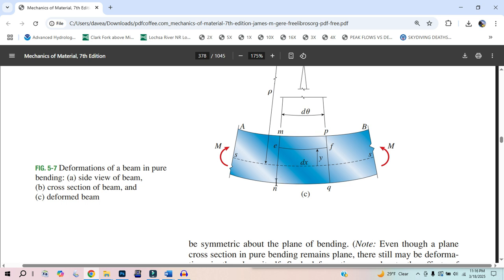so that change in length is going to be a change in length of 2. So the change in length is length final minus length initial. So you'd have 1,002 millimeters minus 1,000, and so you'd have 2 millimeters. And strain is that change in length divided by the original length. So you'd have 2 divided by 1,000. That's 0.002.